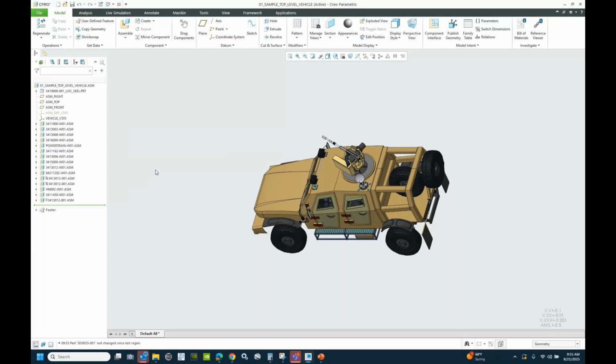But we can create somewhat configurations within Creo by creating what's called a part simplified rep, right? So if I have a very complex part, I can actually exclude features from the part. That would be called a part simplified rep. That does not speed up regeneration because for a part simplified rep, Creo has to regenerate the part first and then regenerate the representation. So it doesn't speed up performance, but it does enhance your display because you're not seeing all the detail of those parts.